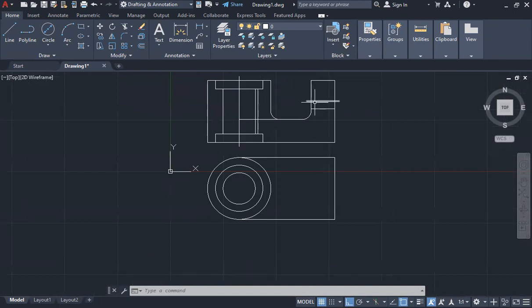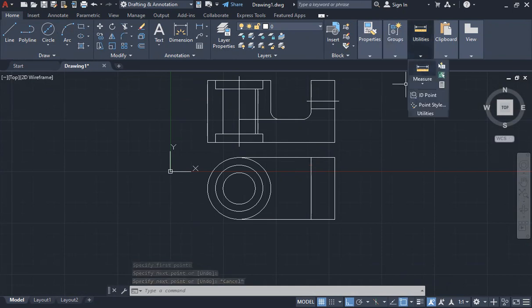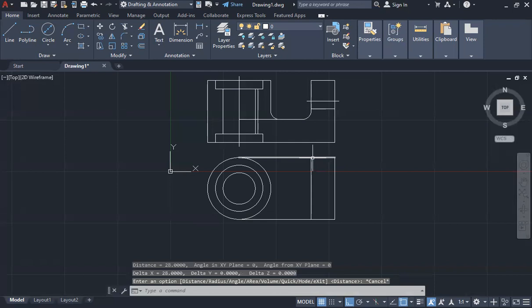So again, for this point here, there's a line that goes right across here. Instead of measuring the distance, 28, and then drawing a line down, I'll start my line command. I want it to line up with this line here, so I'll use this as my reference point, not clicking, moving down. It generates that green path. Now, if I start my line here and draw it down, the distance should be 28. And it is 28.